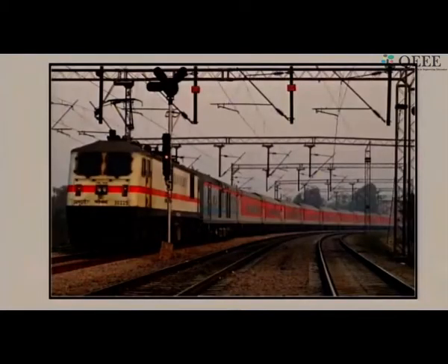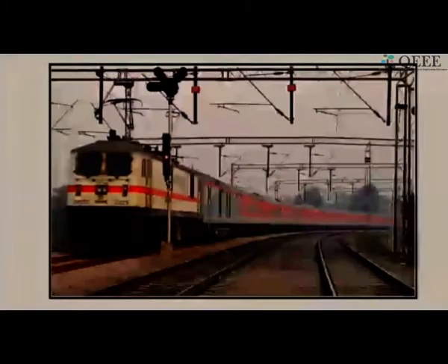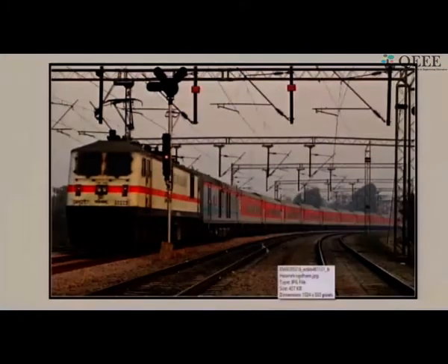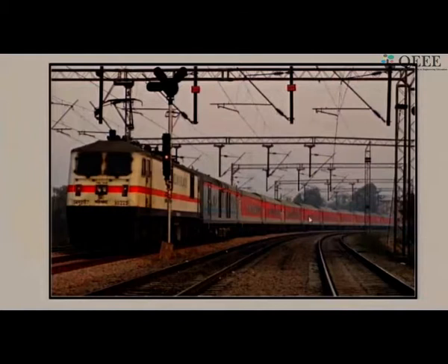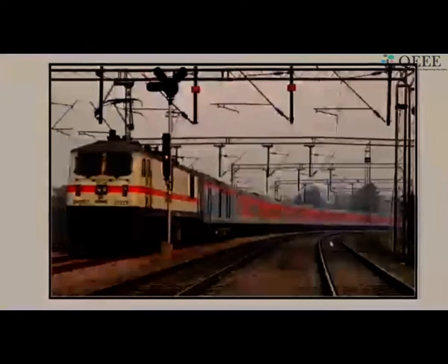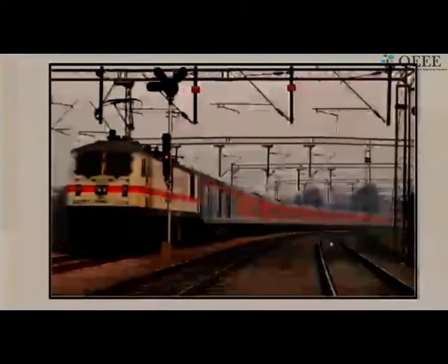This is an example of one of the air-conditioned trains on the railways. The reason I put it up here is that if we want to design the air conditioning system for these coaches, we need to know how much air conditioning capacity to put. So basically there is a certain amount of heat generated inside this coach and a certain amount of energy getting into the coach because its temperature is less than the surrounding temperature. And all of this energy has to be removed by the air conditioning system and thrown into the atmosphere.